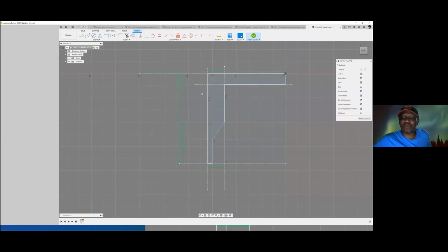The next thing we want to do is to begin to create the positions for the piston rings. When you have a piston, you have piston rings. Those of you who have some experience with motor mechanics will know that we have to create the location of those piston rings. We are going to use the rectangle. We are going to create a 2-point rectangle, and I create a 2-point rectangle here.